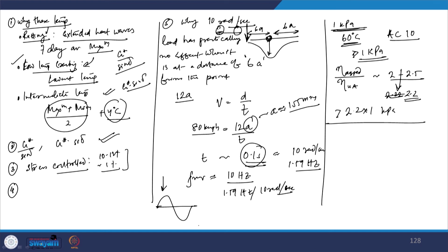Talking about fatigue cracking, again for these binders which were found to be satisfactory, initially they proposed a value of 3000 kPa as the standard. So they said that G star dot sine delta should be less than 3000 kPa.